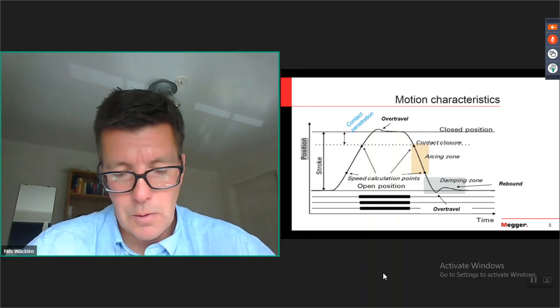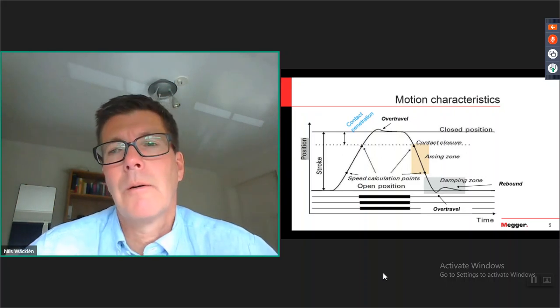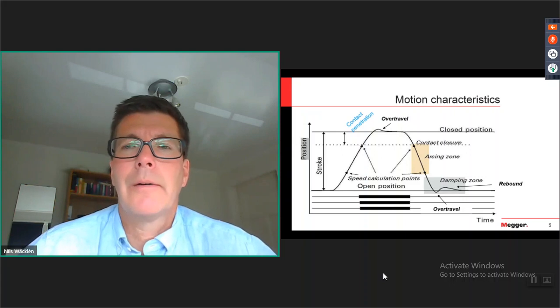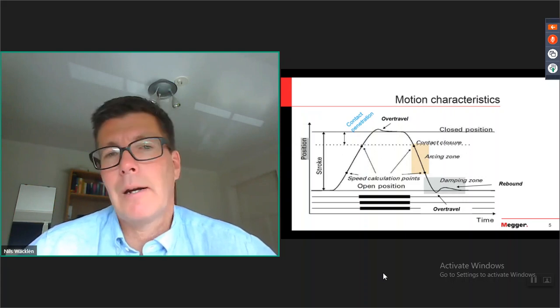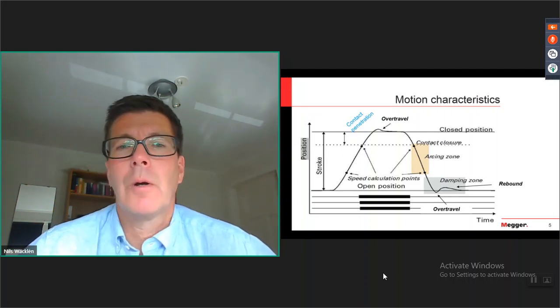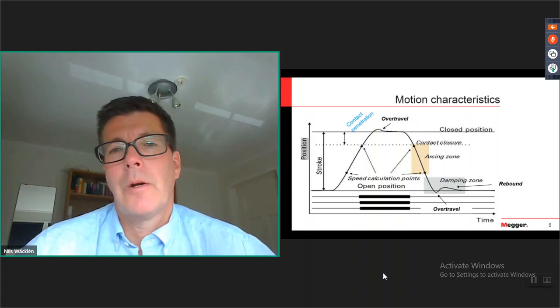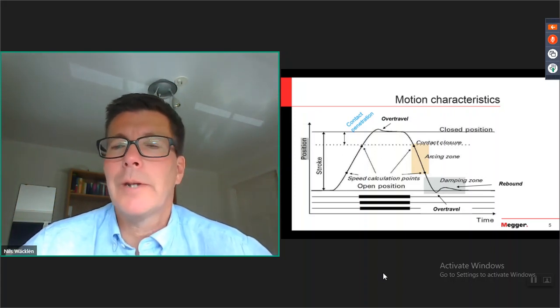can be due to the first touch being the arcing contact when you close the breaker, and the arcing contact is not a very, very good conductor. It can also be burned a little bit. The purpose of the arcing contact is not really to be a good conductor.